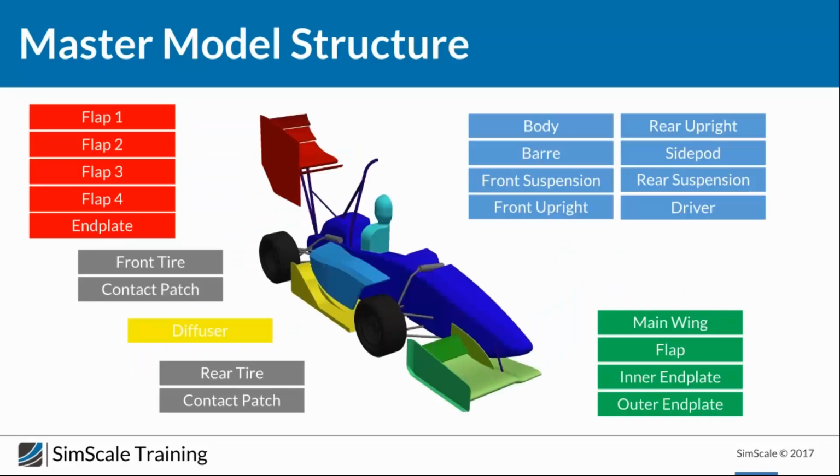Okay, so also one important thing when you work with the CAD and you prepare your geometry. We have discovered what are the different surfaces or models that you can use to model a surface. We have talked about defeaturing the model. And the last thing, when you make sure that you have a clean model, the next step will be to group your model or your parts into groups that will help you later to do a good pre-processing. So you will apply the refinements that you want in the right position, but also later for the post-processing, so you can post-process your results based on the separate parts, but they have connection.